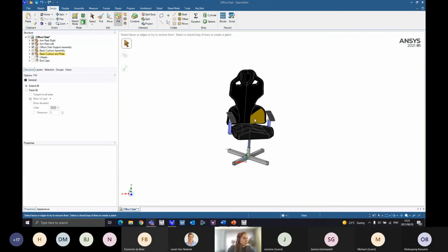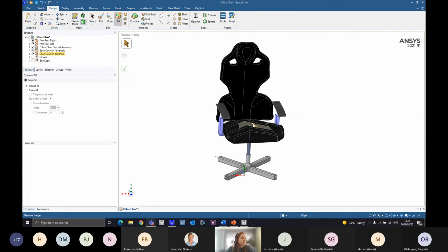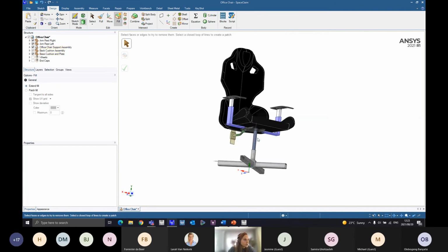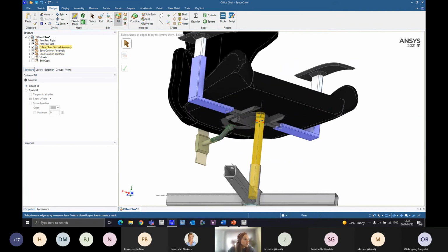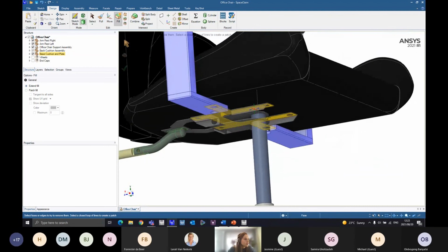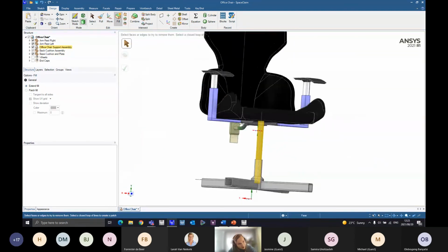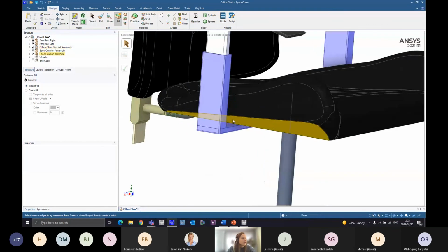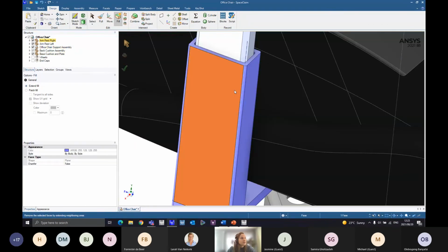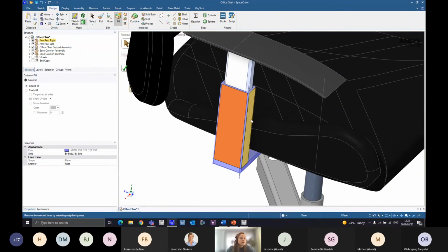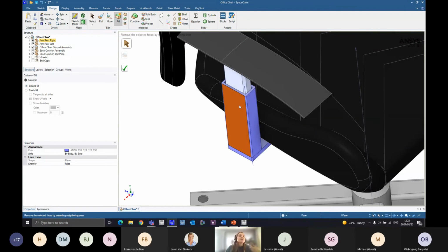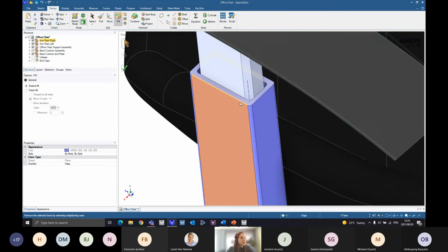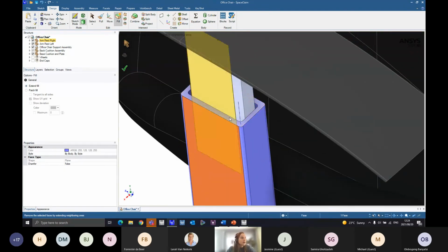Anyway, okay, so yes, as I said, I would like to focus on the mid surfaces today. So luckily over here, there are quite a few components, as you can see, that could be represented by shell bodies adequately. If you had to mesh this body, for instance, with solid elements, it's best practice to ensure that there are 3 elements across the thickness. So that's best practice for finite element analysis.